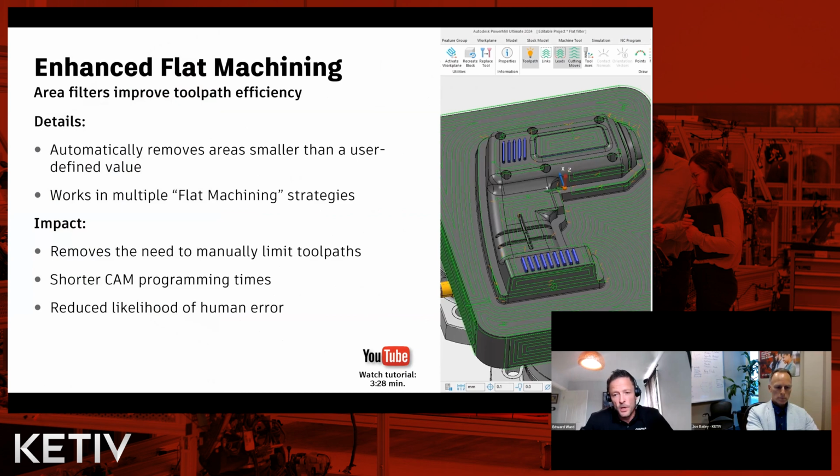Obviously we'll go into it in detail and show you the actual toolpath, but if you look at the picture on the right there, you can see those blue ribs where normally that kind of feature we would be looking to finish in a completely different way, maybe. So we may not want that flat toolpath calculation over those intricate detail areas. Instead of us editing afterwards, obviously it's easy to do, but again, it's extra steps.